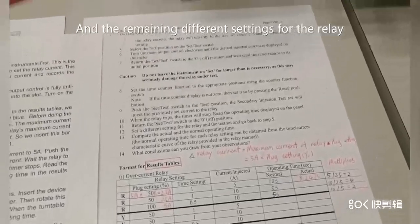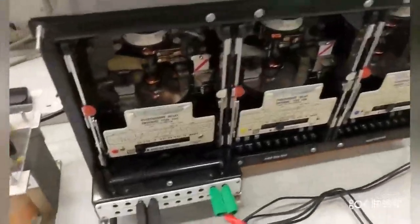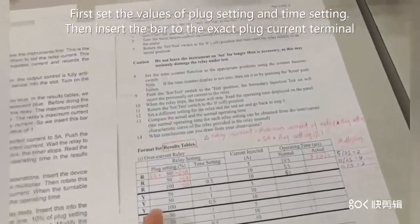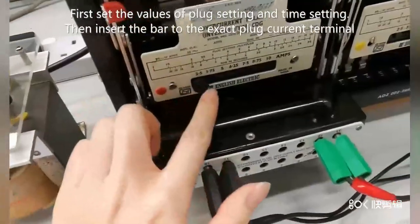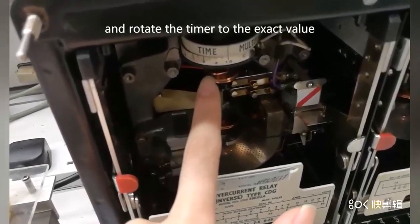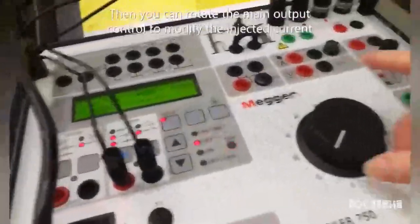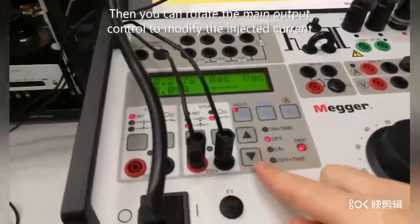For the remaining relay setting tests, just repeat the former operations. First set the values of the plug setting and time setting, insert the bar to the exact plug current, and rotate the timer to the exact value, and then rotate this button to modify the injected current.